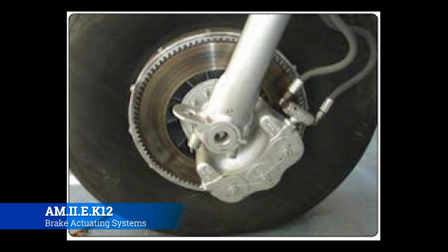Now, I'll tell you that construct of having stationary brake shoes, brake disc, brake linings, all kind of the same thing is very, very common. So on one side they will always be fixed, and then on the other side you'll have the piston that will come out, press on the brake pad, and then push against the rotor, which will then effectively pinch the rotor against the stationary brake pad on the other side, causing the aircraft to come to a grinding halt. And that's how the floating disc brakes are arranged.